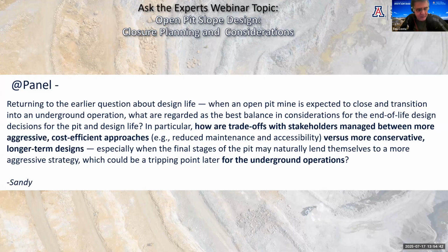I think it could be associated with the type of underground mine operation you have. There's a lot of connection between open pit and underground. If you are preparing your underground for caving, for example, you can increase the slopes, so you can go further and accept less safety, because in the end everything will fail down.